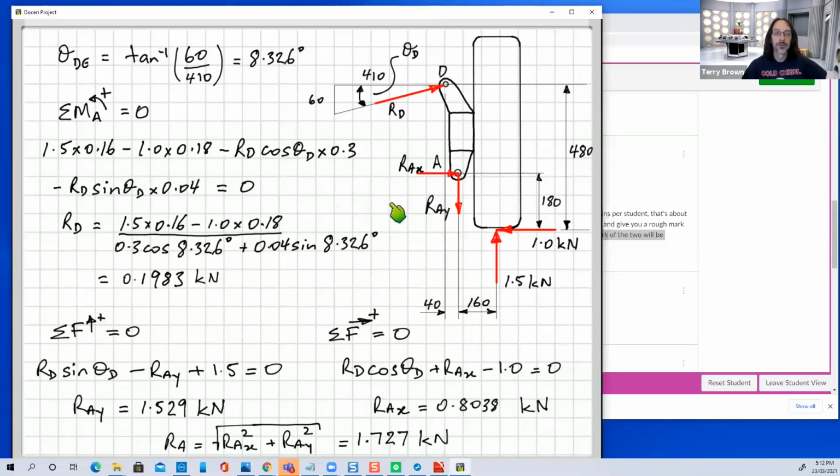to something else. Now that something else could be just a pin connection that's connected to ground, like you would have done in the simple one body equilibrium problems, or it could be pin connected to some other body or some other structural member. Okay, so here it's connected to some other structural member by a pin.